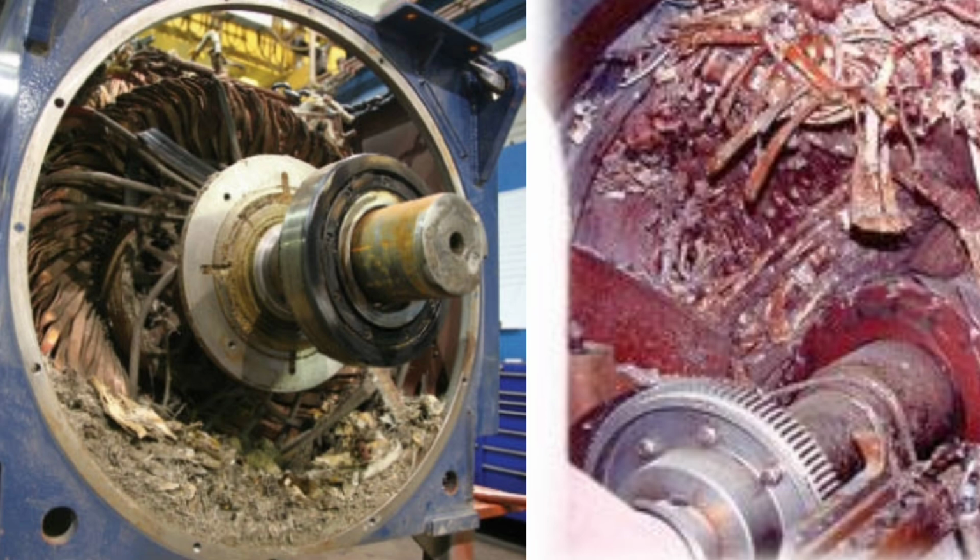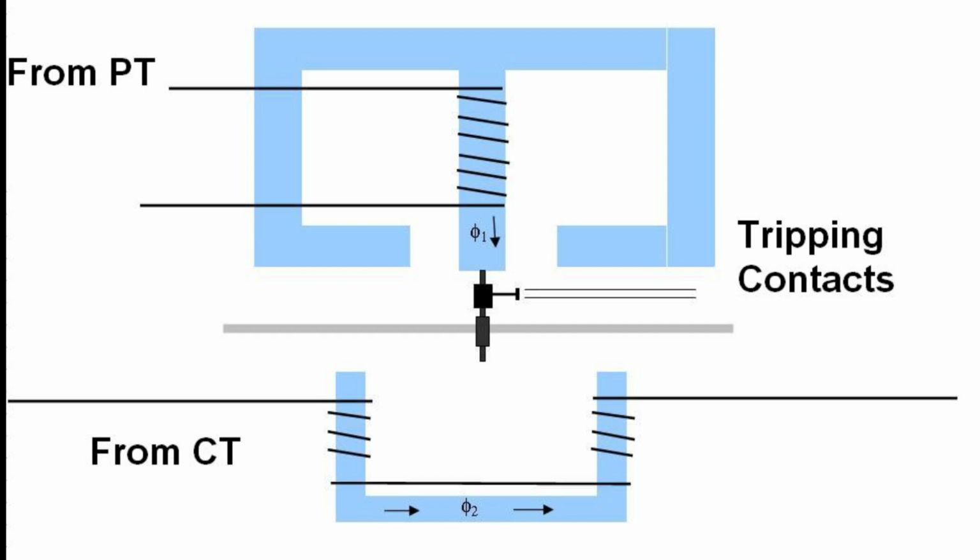In the worst case scenario, the RPM will shoot up, leading to overspeed trip or mechanical failure to the motor or turbine. A reverse power relay prevents all these problems from happening by preventing overheating and possible mechanical damage to the prime mover. It also prevents the turbine or motor from excessive overspeeding to maintain the regular cooling effect of the turbines.